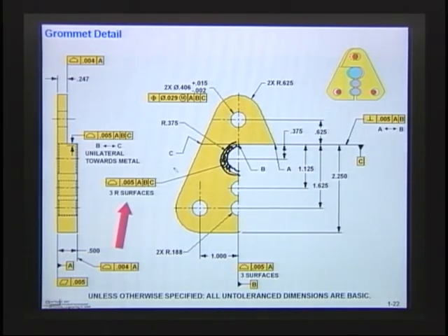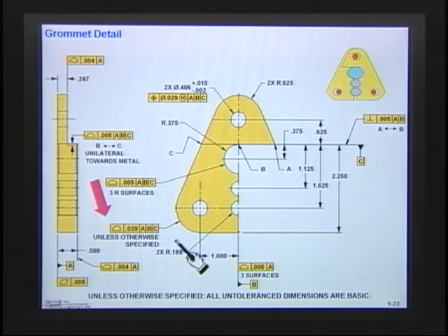All right, let's take a look at another one. You're noticing how nice this profile is. Everything else, I guess I'm getting tired, there's nothing else to do here. You notice as we get further along, down here I say, unless otherwise specified, everything else is profiled within 20 thousandths. So I have a large profile tolerance, and everything is covered with a profile tolerance. That's my largest tolerance. So that's what this does, profile within 20.